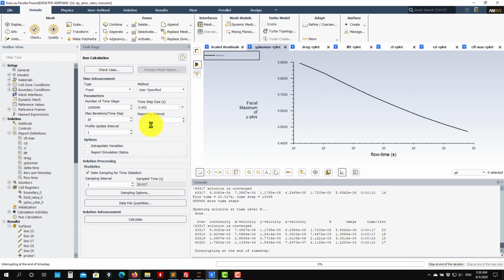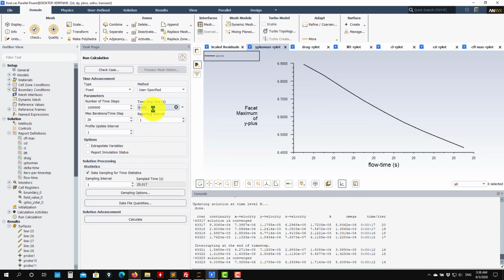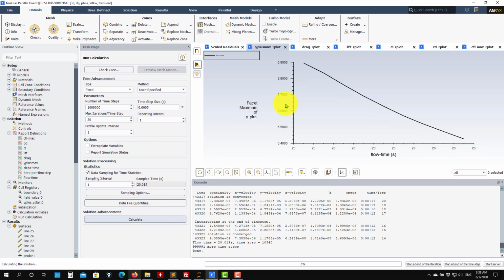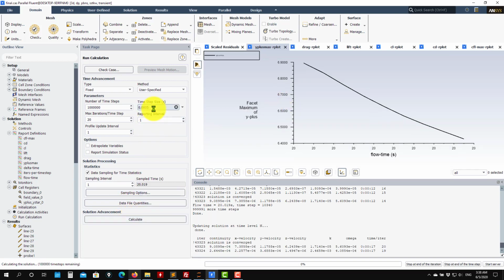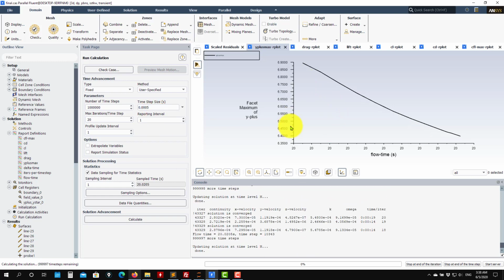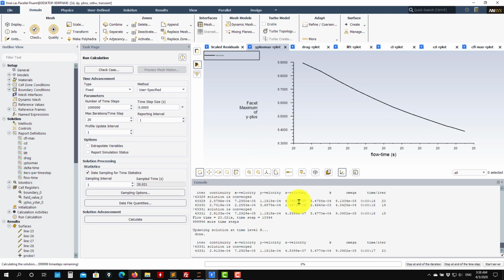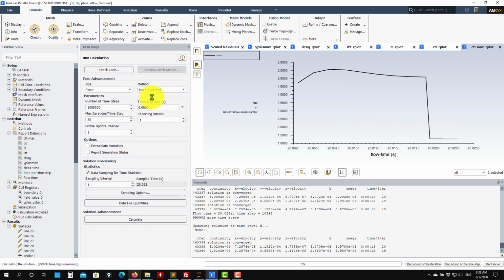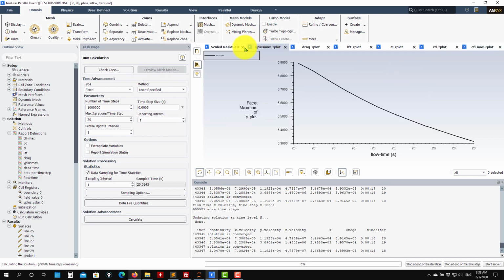So let me stop here, and this will require quite aggressive time reduction. So see that I will need to go to 0.0005 to probably get something about 1 or 2. Okay, I need to check this one. Okay, yes, about 1.2. So this will be my time step. So see that it's converging in about 3 iterations. Ideal, actually, is 2 iterations.